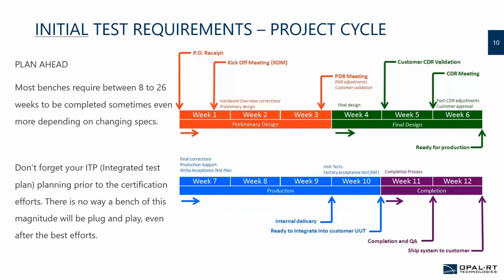Also, it's not written here in the timeline, but you definitely need to have an ITP, integrated test plan, added at the reception of the bench on your premises. Why is that? It's because as good as we are, as good as our intentions are, even if we evaluate everything to the smallest details, there will always be something that will differ from reality.